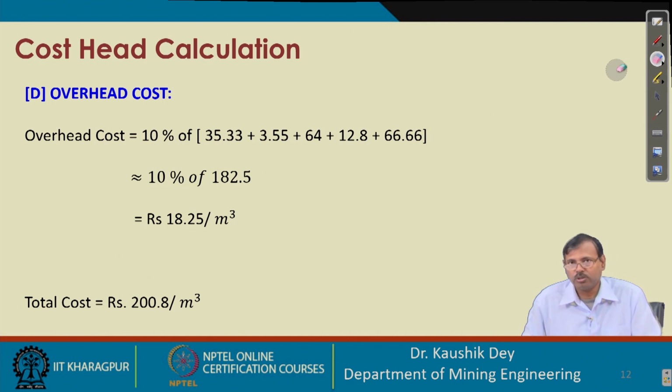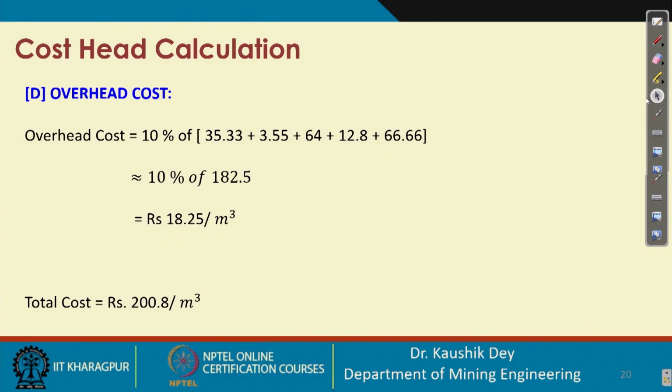So, other cost components, like in capital we have not considered interest, we have not considered depreciation. Similarly, in maintenance also we have not considered many consumables that may be there. There are some critical conditions that may arise in case of jumbo drill. Often you will find that in a jumbo drill, the drilling is basically carried out with electrical motor, but often the propelling is made by the diesel engine. So, jumbo drill may have the provision of diesel and electrical double power system.